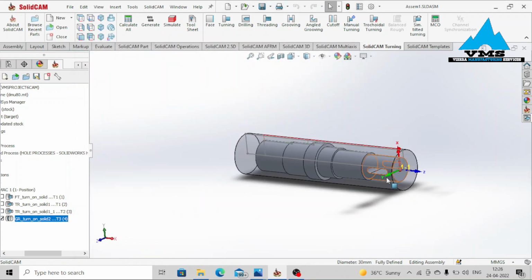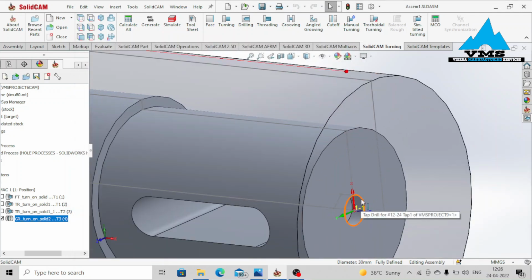So we are almost done. So let me calculate the drill diameter. So it's going to be 4.5 mm. There are actually two ways in order to make this hole. Now the hole is 4.5 mm. So either you are using a drill of 4.5 mm, or I could use a drill of 4 mm or 3 mm, and then in order to finish the hole, I'm going to use a boring tool.